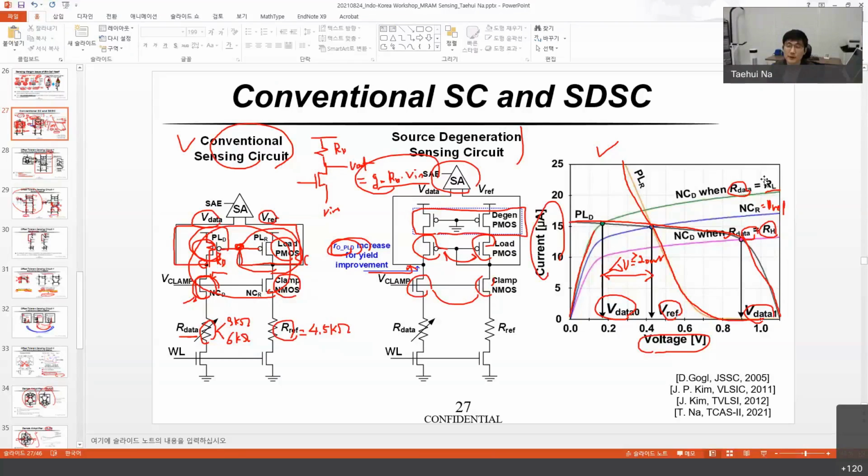Well, if we compare STT-MRAM with other non-volatile memories, such as the other emerging non-volatile memories like RRAM or phase change random access memory, the target application is very different. In the case of RRAM or phase change memory, their major target is to replace SSD, the NAND flash memory, or aggressively to replace DRAM, for high density memory. The reason they have this goal is that they are mostly 3D stackable. In the case of phase change memory, you already know the Optane memory by Intel has 2 layers, and the 4th layer is also available nowadays.